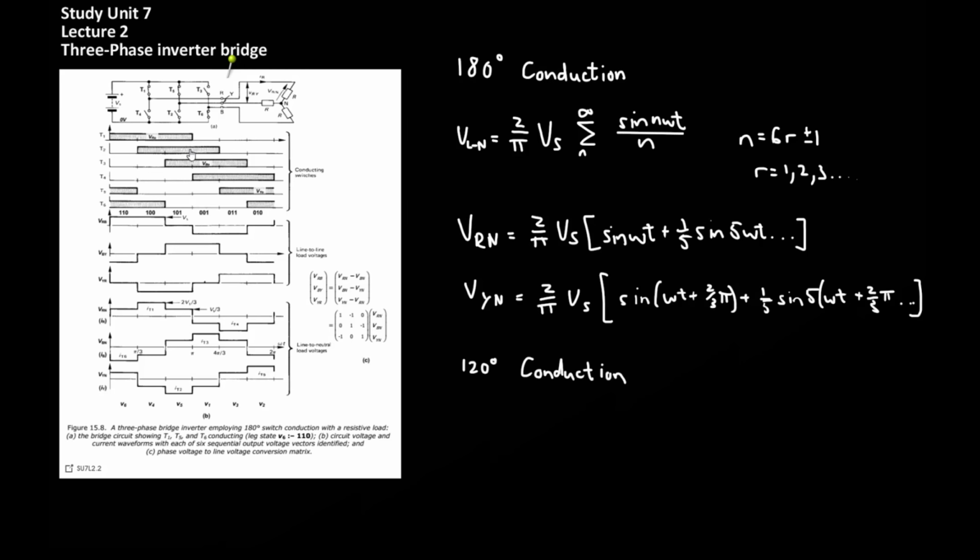So there are several techniques which can be applied to modulate the frequency and output voltage for these DC to AC converters, and I'll quickly touch on some of them throughout the lecture. Just to list the main ones which are referenced in the reference material, there is variable voltage DC link, single pulse width modulation, multi-pulse width modulation, multi-pulse width but with selected notching modulation, sinusoidal pulse width modulation, triple N injection, and finally selected harmonic elimination. So some of these techniques are fairly simple, others are far more involved.